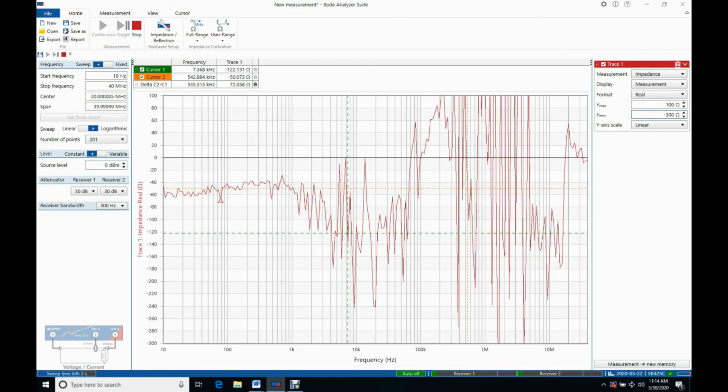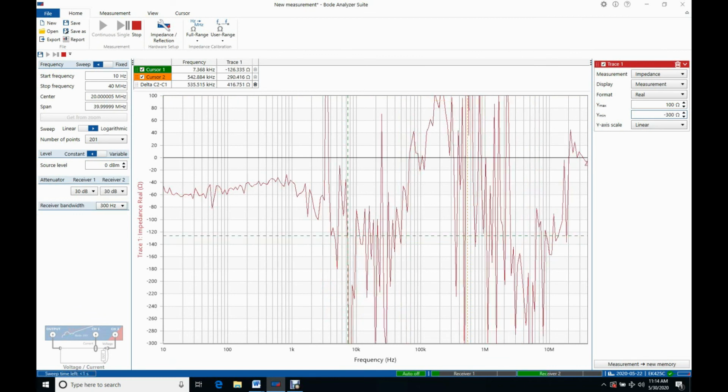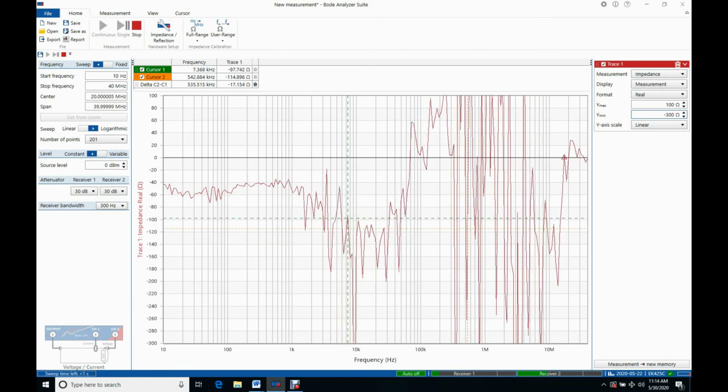during the bandwidth of the control loop. Okay, and then once the control loop can't control it, then it goes to the positive. But this is neat to be able to see this. Like I said, this is the first time I ever did this type of measurement, and I think it's pretty eye-opening that the concept of negative resistance is something really real. That's an actual physical effect. Okay, the measured negative resistance is very close to what I calculated.